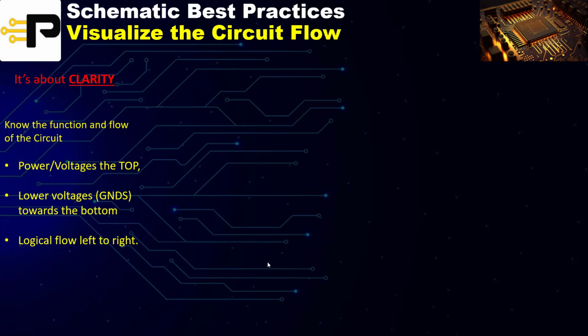A couple things here. First off, know the function and flow of your circuit. Many times designers do not know the function of the circuit they are designing. So it's very important to understand that first off. If necessary, get into the data sheets, understand what the components that you're working with do and what that circuit is supposed to do. Secondly, understand the power and voltages.